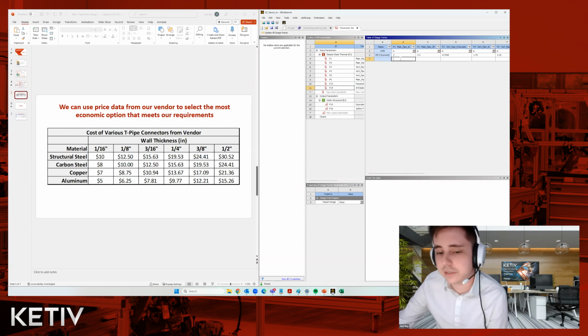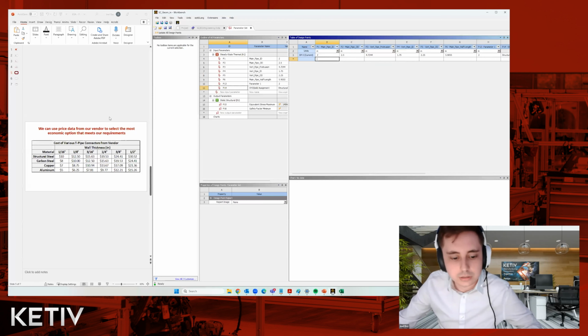We started out with the 1/2 inch, right? Because the outer diameter is going to be fixed, because our external geometry is fixed, we're just going to be adding size to this inner diameter of both the main pipe and the vertical pipe. So actually, let me make this a little bit bigger and zoom in here.